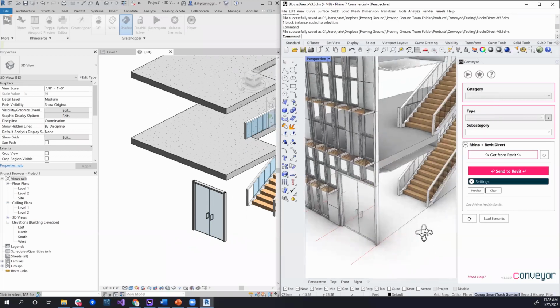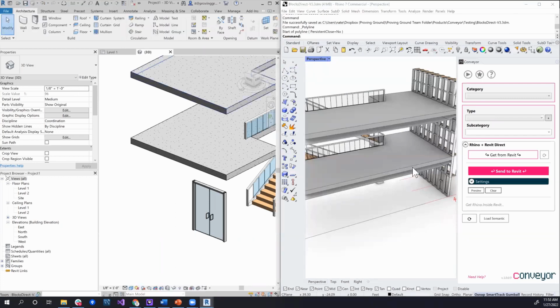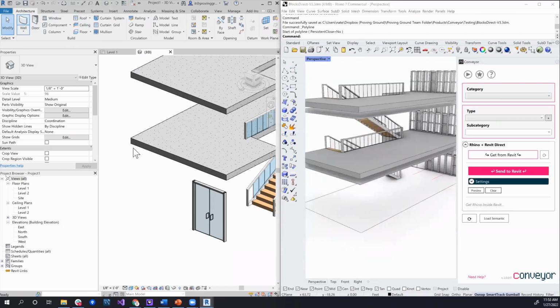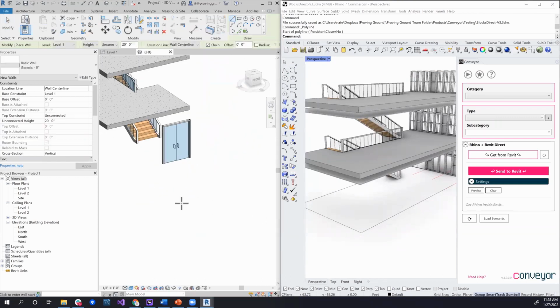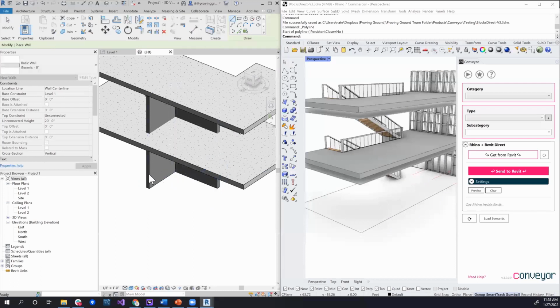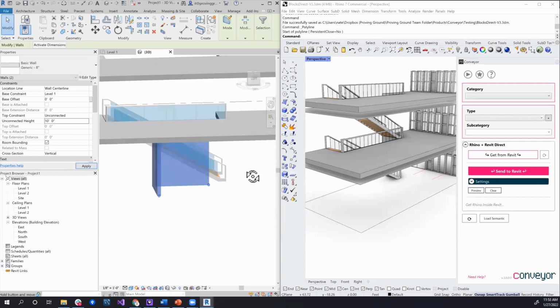This also works the other way. I wanted to highlight that other direction here with Rhino Inside, wherein I might have something like a couple of walls in Revit that I might want to coordinate with my Rhino model, whether it's for visualization or I need to work around them for a different design activity. So I'm going to sketch in a few walls in the Revit environment. Let's say a couple of tall walls going up a couple of stories. And maybe I'll make these a little shorter. Maybe 10 feet. Yeah, these are 10 feet. There we go. So I've got a couple of partition walls there.